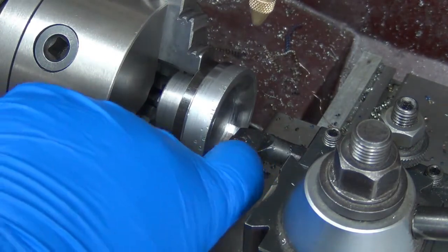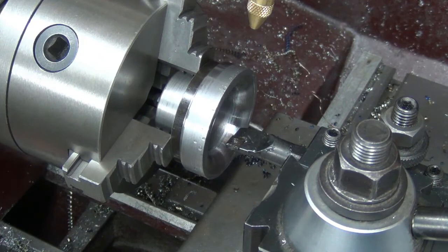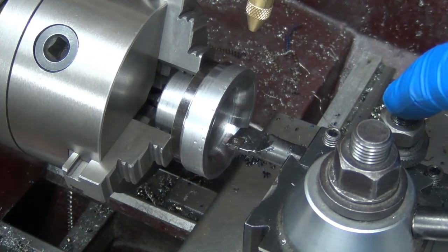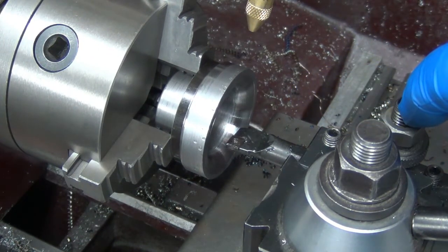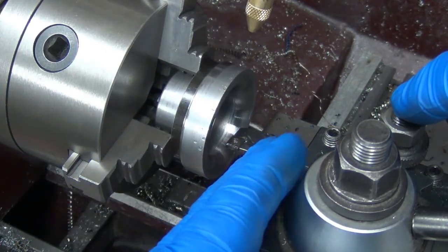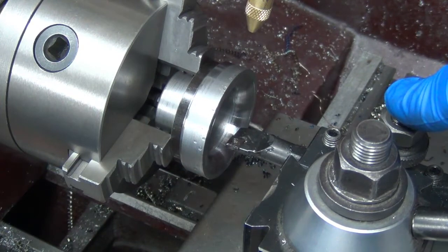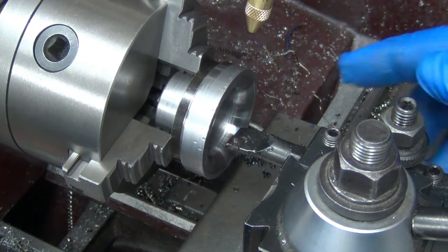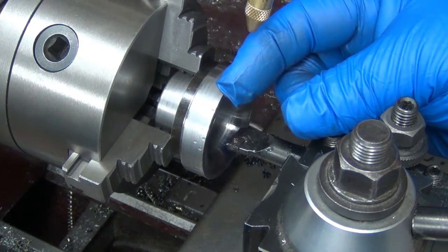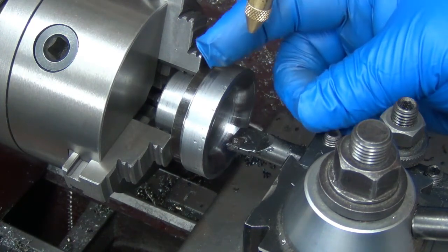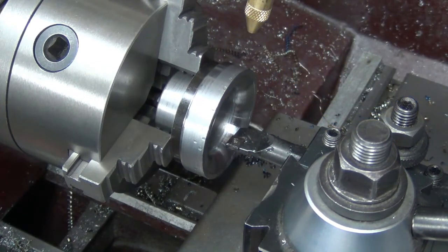Well, you can see that lip there. I don't like that. Not quite sure what's going on with that. The only offset I've changed so far in the tool table, I've had to readjust the setting between tool 1 and tool 2 on the X. I have not done anything yet with the Z. So apparently I'm going to have to check that and tell it to change up the Z a little bit. So since it cut in further, it thinks the offset is smaller than it was, and it moved the whole thing further. So I need to go in and tell it that it's longer right now, so that way it won't go in as far. So we'll go change that here real quick.